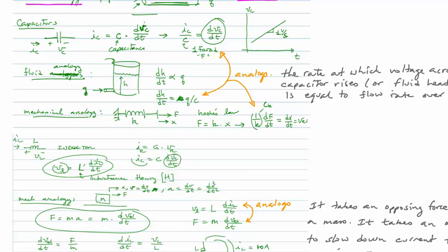So this is the symbol for a capacitor. Again, we have current flowing into the capacitor, or through it, from the left with the polarity plus and minus. And the constituent relationship, or terminal characteristics for a capacitor, i.e. the relationship between terminal current and terminal voltage, is as follows. The current and voltage are not proportional. Instead, the current and the derivative of the voltage are proportional. Okay? Current and the derivative of voltage are proportional.